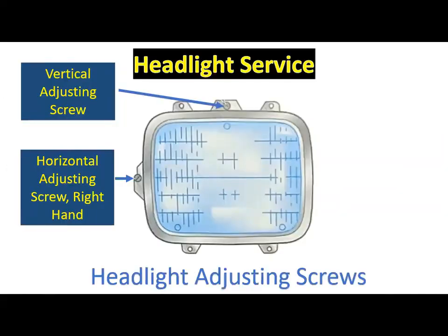The most common headlight service is changing and aiming headlights. The headlight replacement procedure varies depending on the vehicle and the type of the headlights. Be sure the headlights are turned off before a headlight replacement procedure. When these lights are turned off, there is no voltage at the lights, therefore battery disconnecting is not required. So you may not disconnect the negative battery cable from the battery terminal.